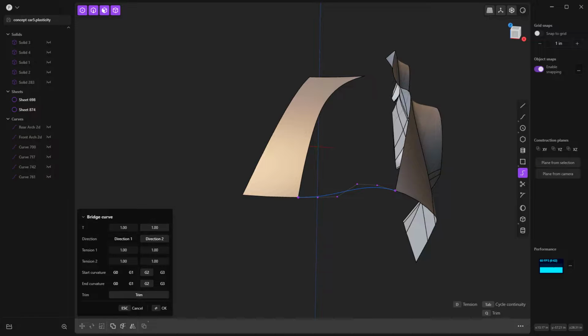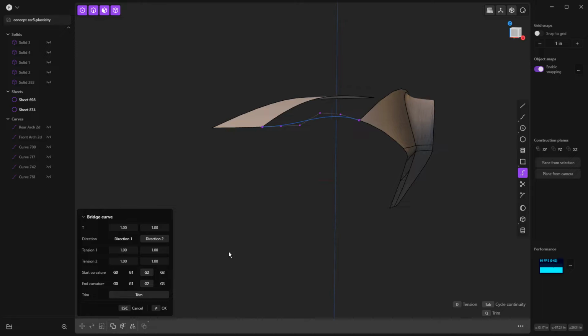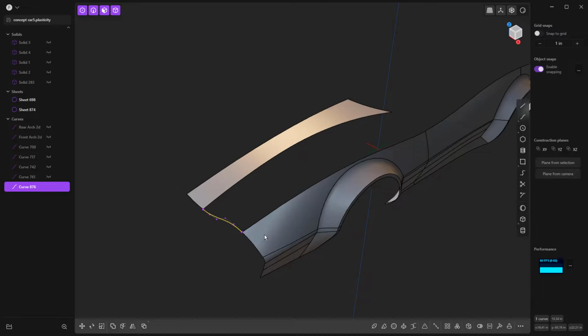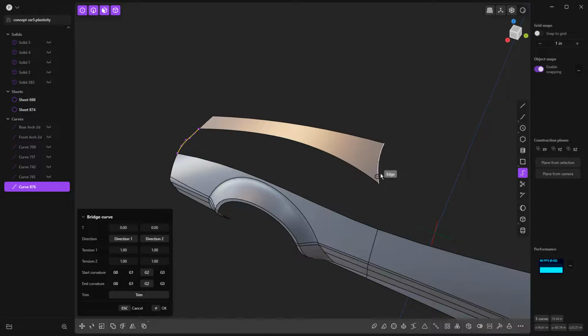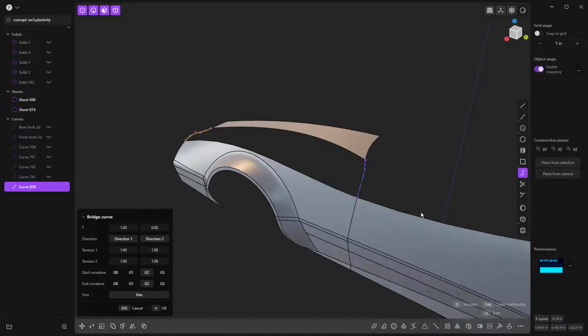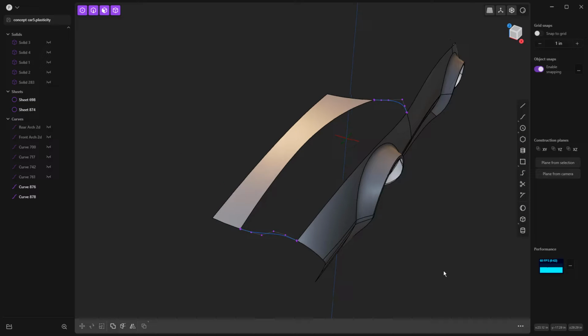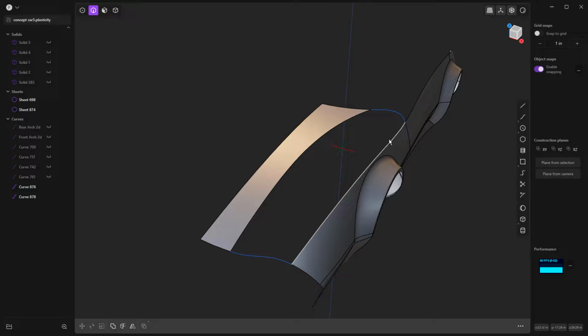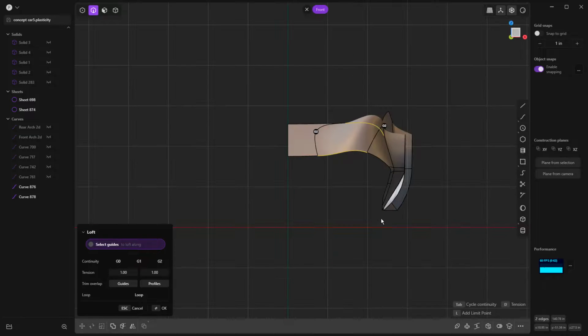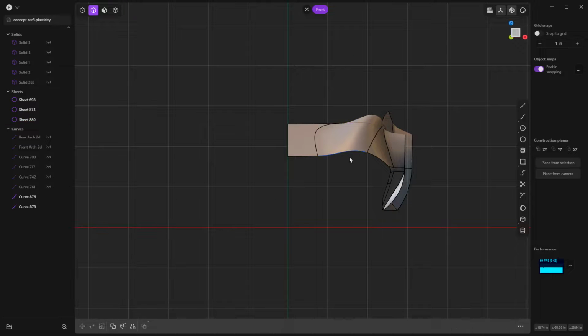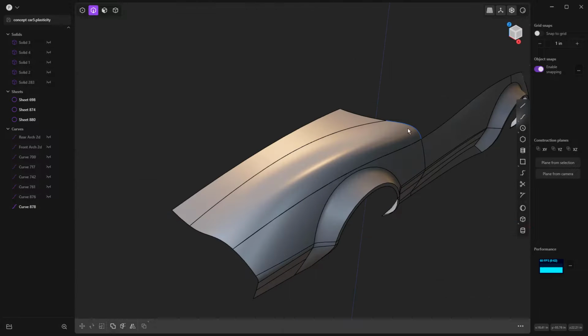So that's at 1, that's at 1. We use G2 continuity for both. And let's just try it on the back end. Let's see what this looks like. So from there to there, 1, 0. I think the A pillar is going to be pretty tricky on this, but that's okay. We're just still playing with shapes. We'll loft, shift select these as guides, make that G2, G2, and let's accept it. So hide these, hide that.